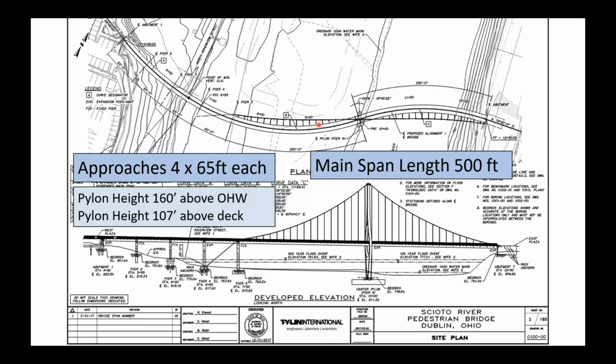So the sum of these lateral components of the cable loads is balanced by the lateral component of this tie-down hanger. And then the axial component of the main cable is balanced by the axial component of this, so that we don't get a net longitudinal demand on the pier. At the same time, we don't get a net lateral demand on the pier. So really, we did that to balance all the loads.